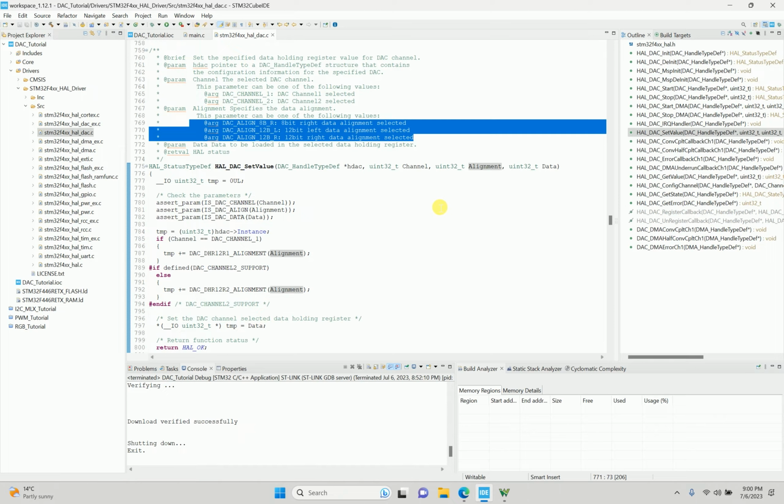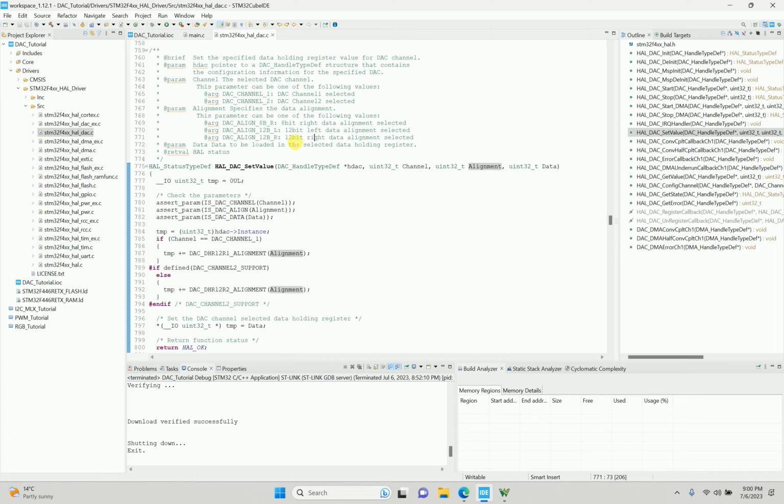We'll be using a 12-bit setup, and then we want the data to be aligned on the right side. So there's a register where there's a right side, there's a left side. So when you go onto the data sheet and look at that register, this is a better choice, because when I look at the oscilloscope, I see something that makes sense to me.